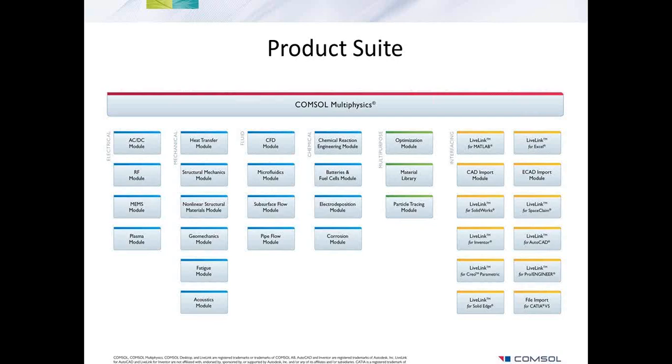Yeah, this is a little bit specific as far as going into the COMSOL interface is concerned. I believe you already have access to COMSOL, so I can give you the specifics. You need to create something known as a 1D plot group, and then you need to add something called a point graph to that 1D plot group branch. In that way you can select whichever point you want to.